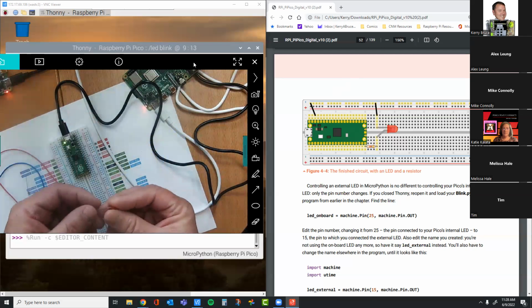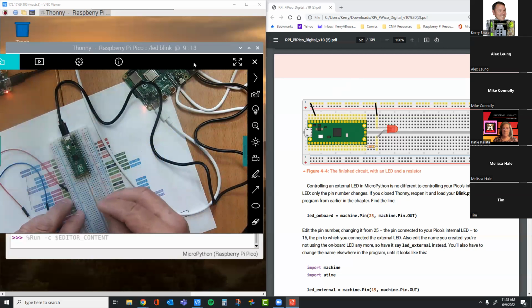To put this light in, it can go anywhere. On here, we're going to go relatively close to this because we're going to bridge that resistor. I'm going to start to insert one wire, then line up the other wire, and then just put the LED down into the board. You can bend it so you can kind of see.